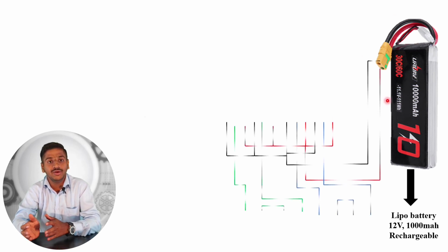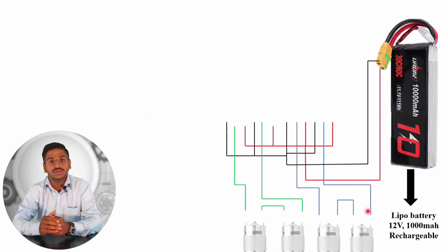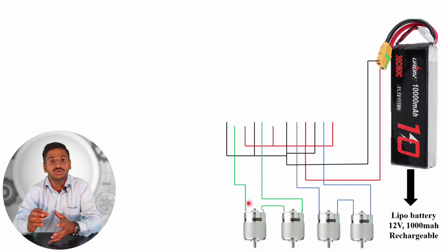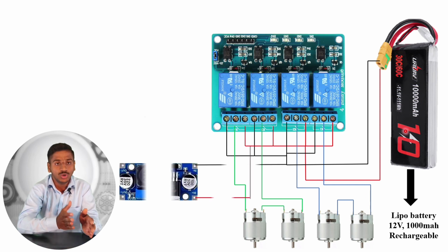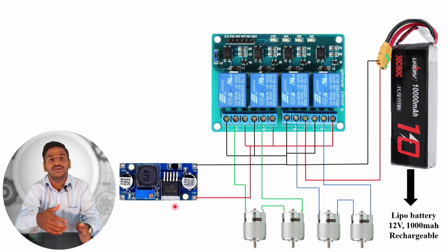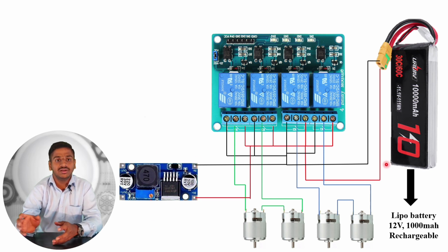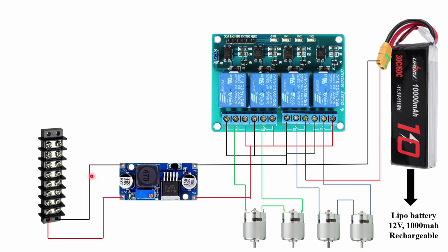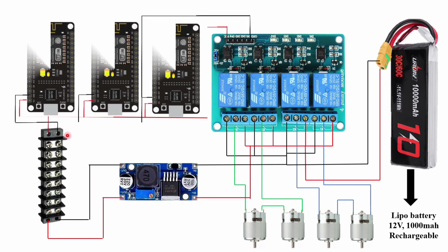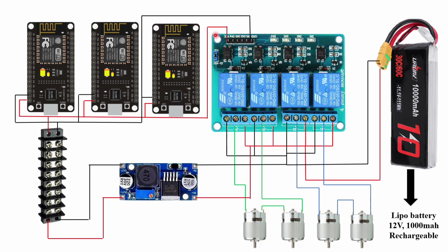And then on the side you can see there is a buck converter. What the buck converter does is convert that 12 volt supply into 5 volt, and then that 5 volt is given to all the NodeMCUs and the relay module wherever it is required. So I have just created one module also. We have connected jumpers in a series manner, so that every connection goes for the 5 volt and a ground connection, that is -1.